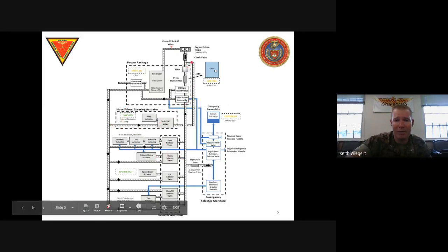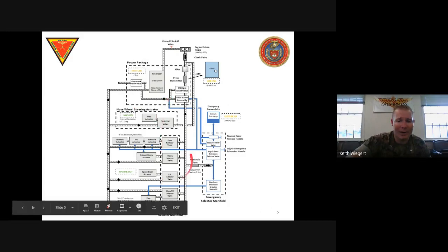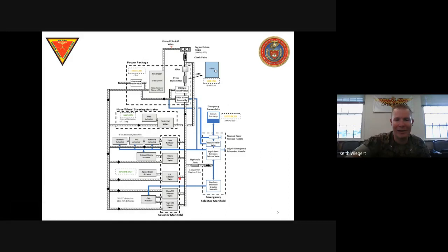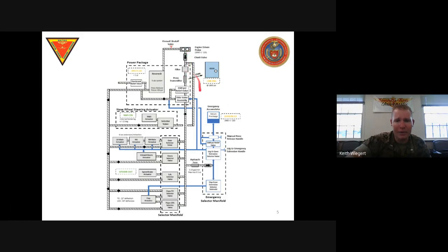So it does get tapped off from the power package, right? And come down to move the nose wheel steering, right? That's because it doesn't necessarily take 1,800 psi to operate the nose wheel steering, and it's kind of a nice to have component. So if you don't have the nose wheel steering, that's fine. But if the pump is still producing power, then we can still have some kind of pressure. We can still have nose wheel steering even if we have gone to the emergency side if there's any pressure available up here. That's the way that does work.